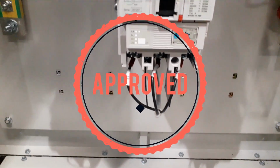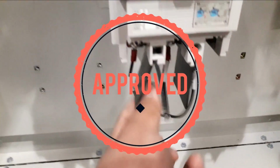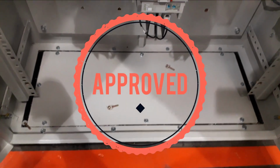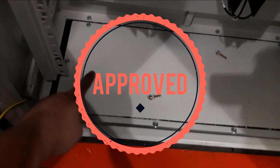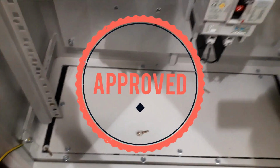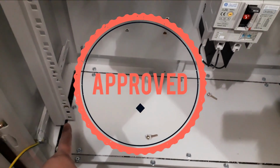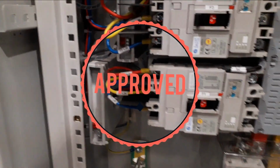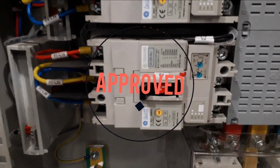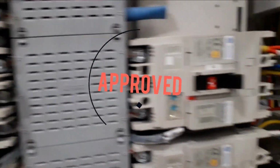Okay, so this is the terminal that you are going to terminate your incoming cable to. This is line 1, line 2, and line 3. Okay, and here you have the opening gland plate. So in this point, you can make a hole here to make a glanding hole, in order to pass your cable from here through our toroid. So both of these are available already here. This is the branch breaker number 1, branch breaker number 2, branch breaker number 3, and so on. So you will find them from here.